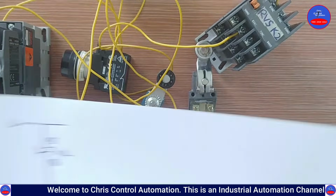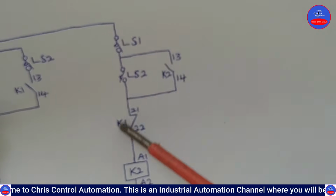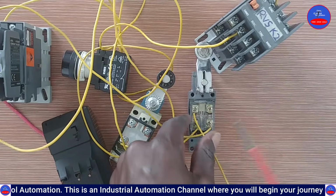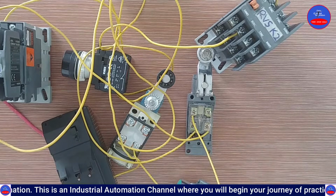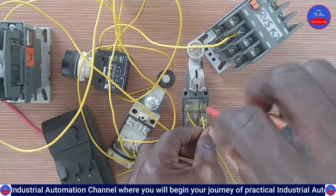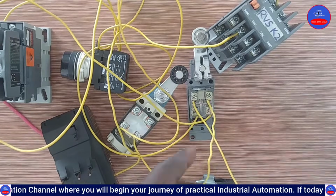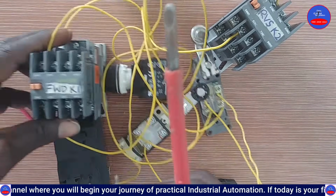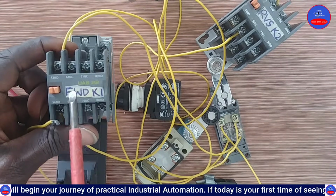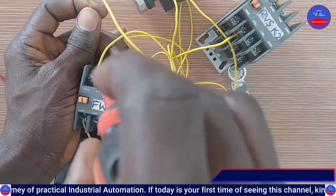and then from the down, it's going to the close contact on contactor 1. Okay, so from the other side, let's pick a cable, put this one here. All right, so this is contactor 1, close contact. So we have 61, 62, the same thing. So we place it here.